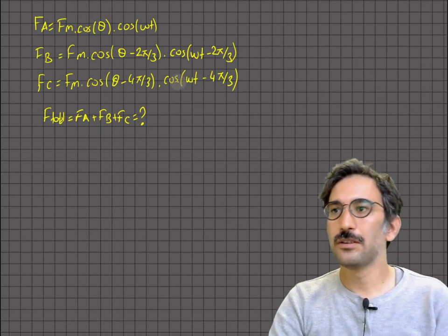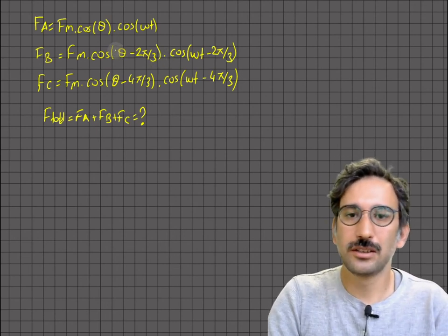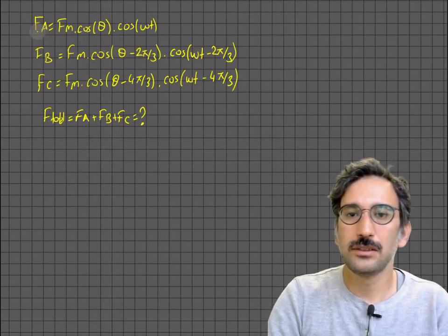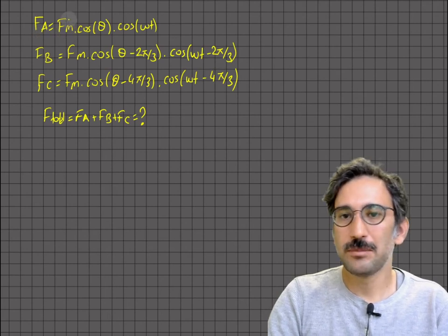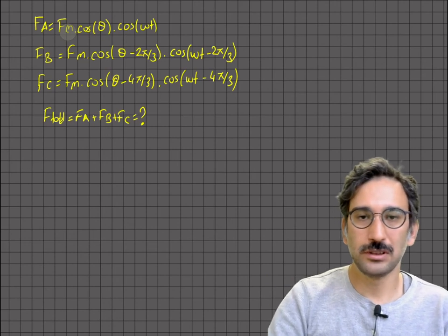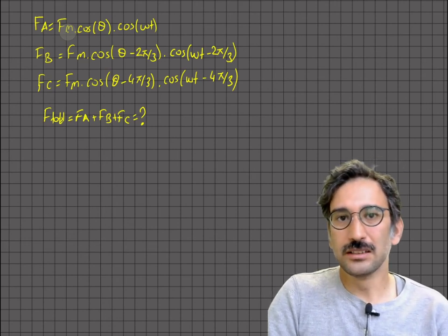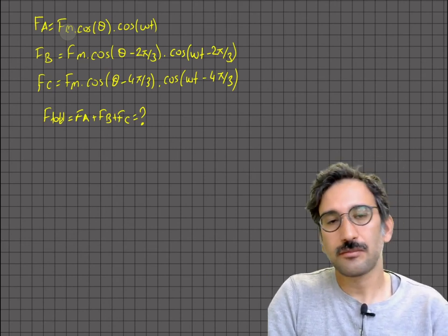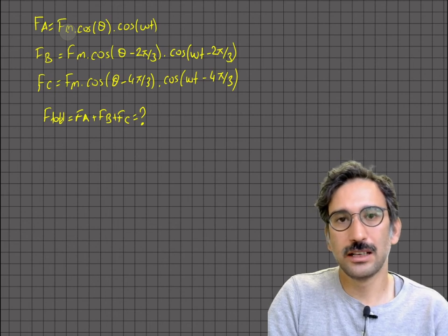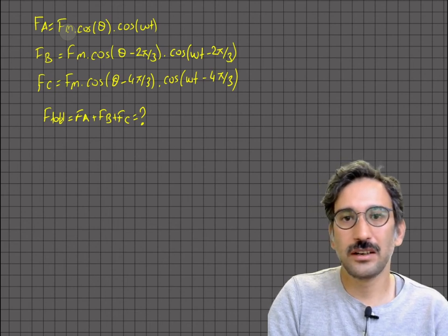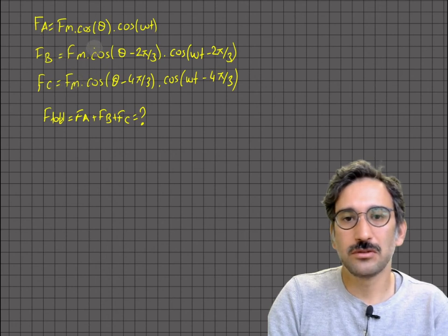Okay, so I have written here the correct term. The MMF of phase A is equal to Fm, the maximum value depending on the current and the number of turns. Both the current directions and the coil dimensions are equal, so we have the same maximum Fm between those phases.